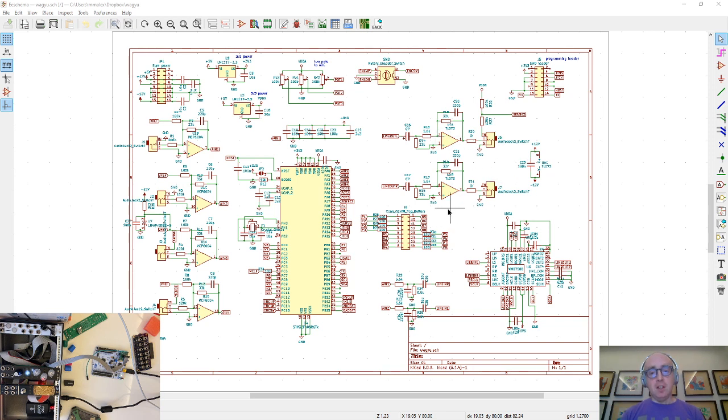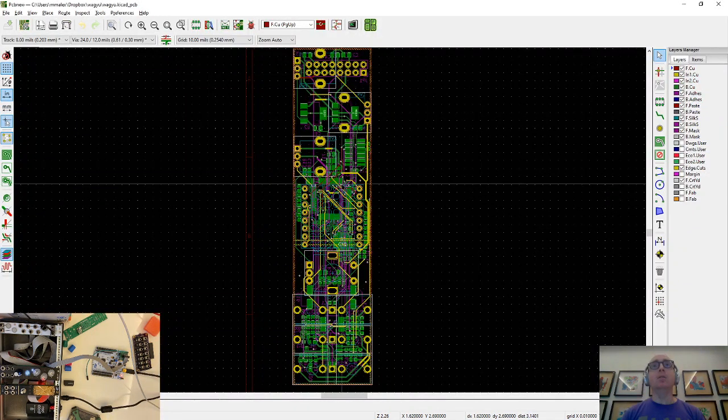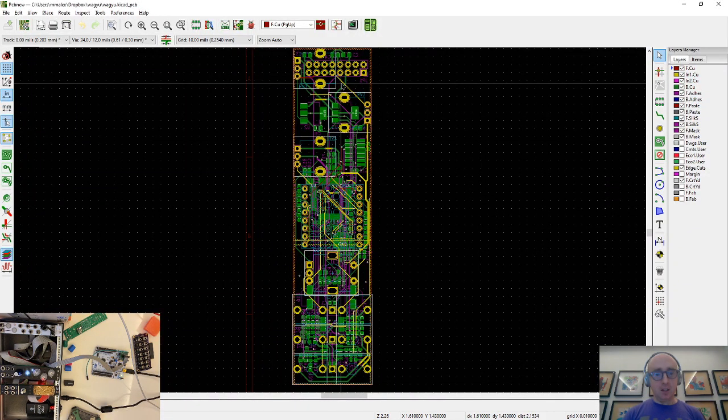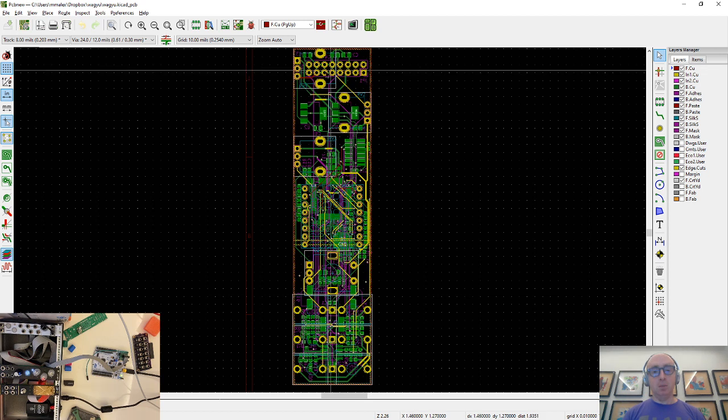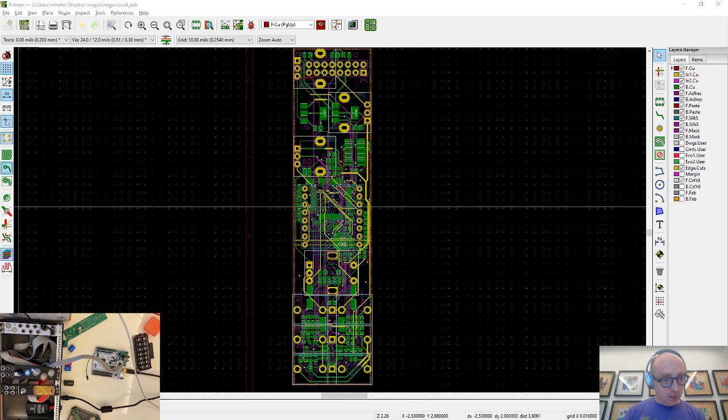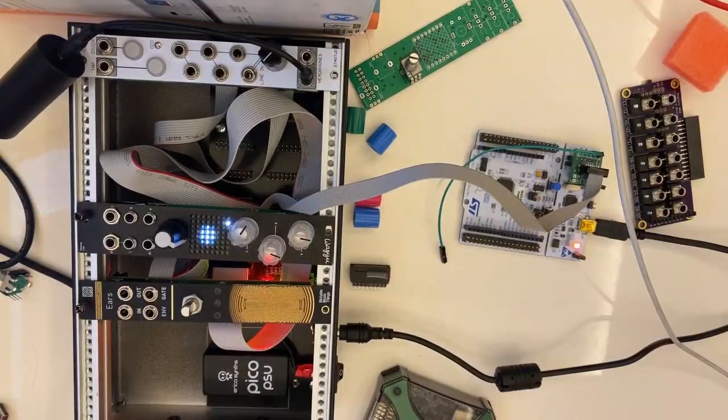And then in terms of the layout, I did a 4-layer layout, which is really gross, and I made a minimum of 3 mistakes. So one mistake was that the 16-pin eurorack header I didn't completely center, and I totally could have. And as a result, it very slightly overhangs the board. In fact, I can show that on the overhead view. So if I just switch back to the overhead, check the chat.